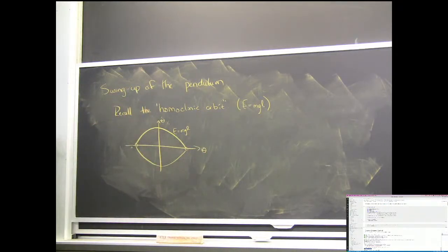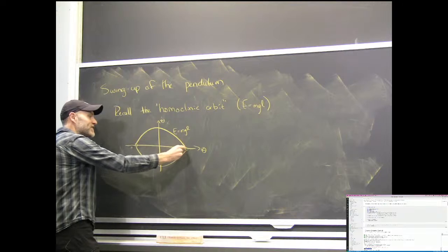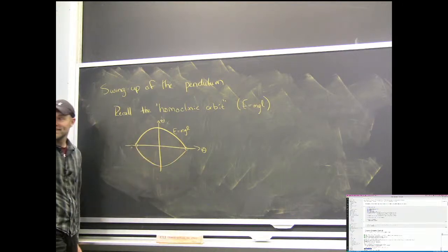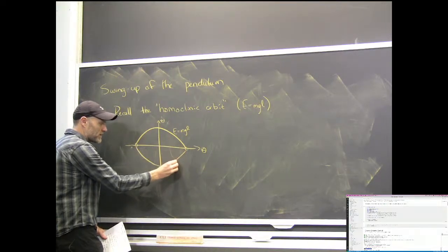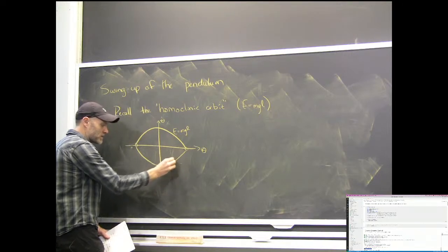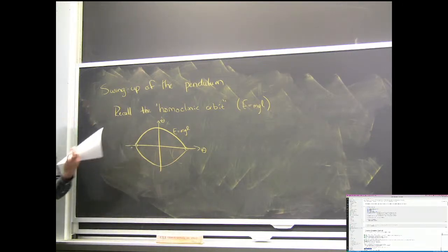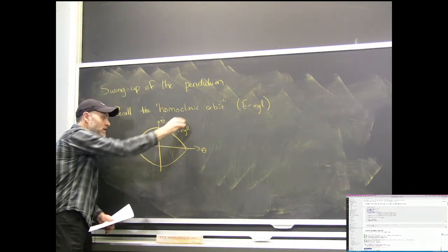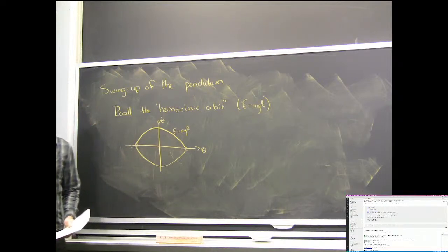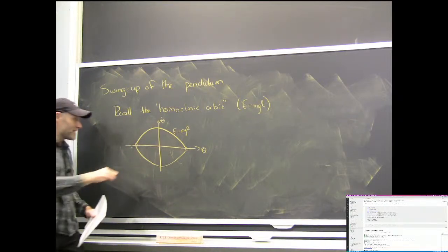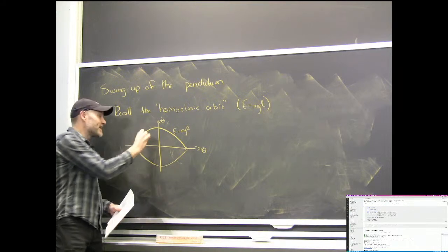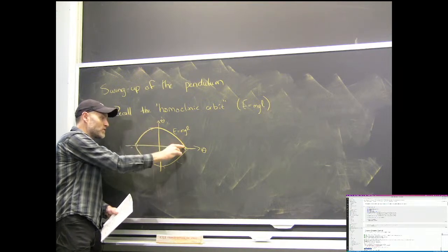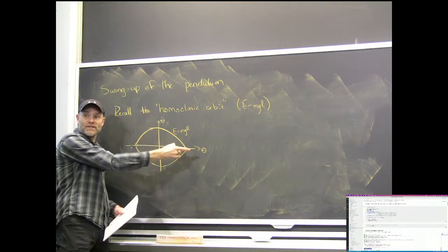Okay, so here's my idea for swinging up the pendulum. I'd like to make a Lyapunov function that's 0 is obtained on that orbit. And I want to kind of have a quadratic form. I can't draw it very well here on the board, but I want to have a quadratic bowl that kind of goes away from the eye, right? So it'll be higher here, and 0 there. And if I can have a Lyapunov argument that drives me towards that eyeball, then I know actually the trajectory will eventually drive me over to here. I'll just ride the wave.